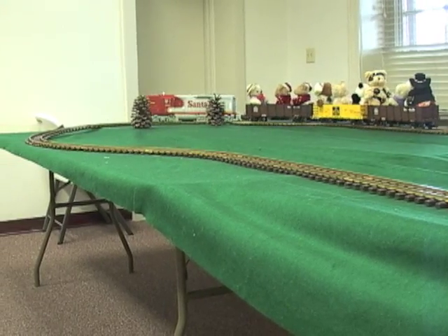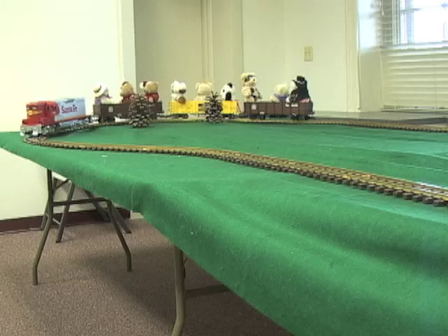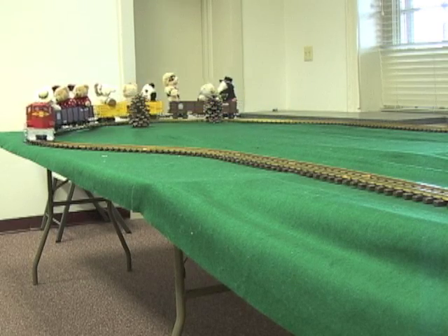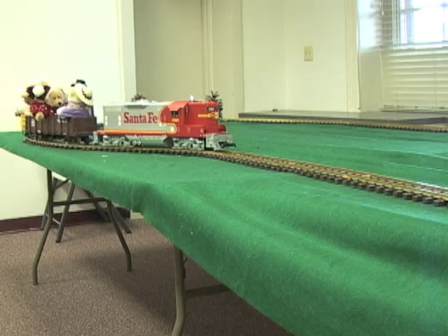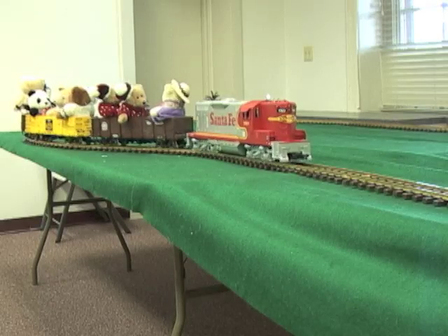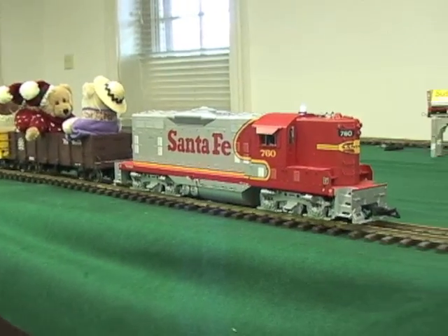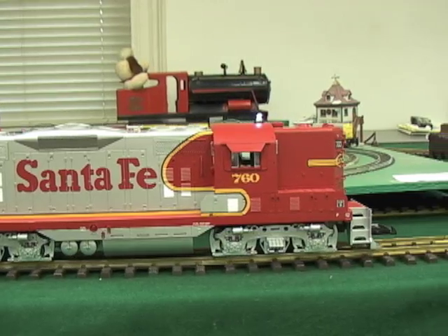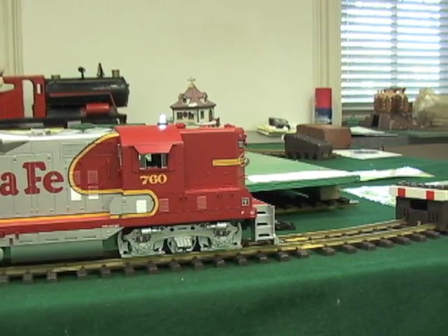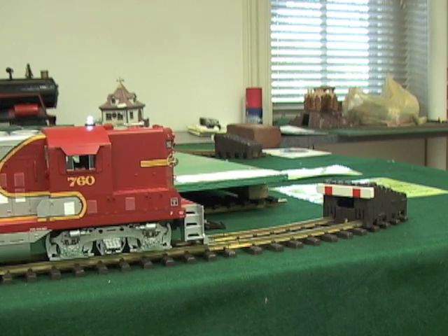This train's running point to point. Once it blows the horn, there's again a wait statement. It's looking for a reed switch this time. There's reed switches in the track at each end of this semicircle. So when the engine goes over a reed switch, the magnet on the bottom of the engine will activate the reed switch, and the mini panel will slow the train down. So it'll sit here and idle for a minute, and then it'll start back up in the reverse direction.